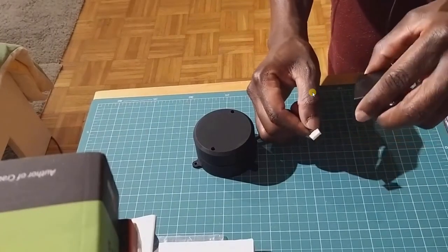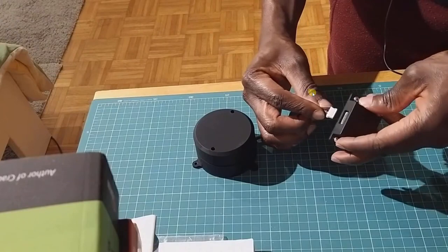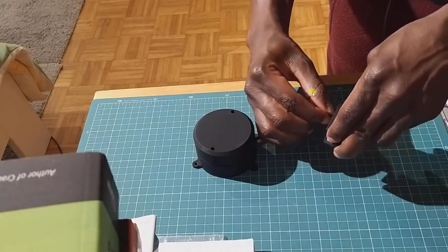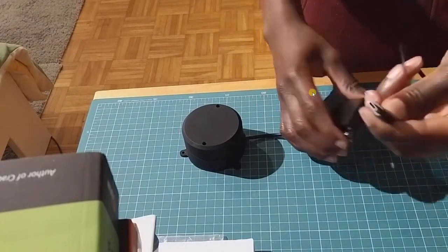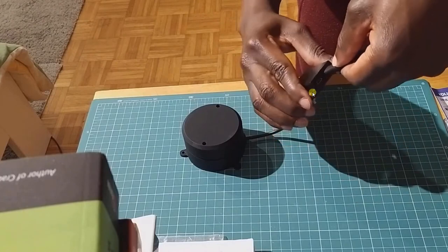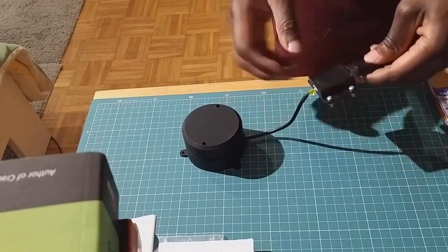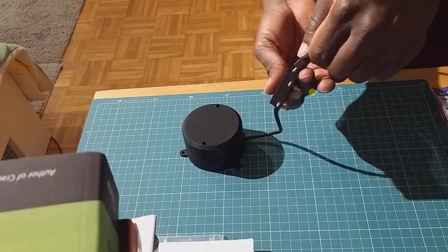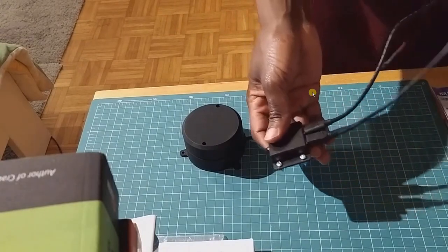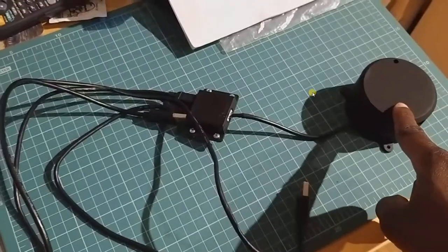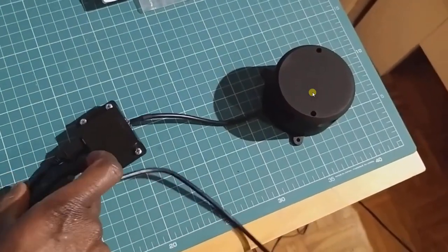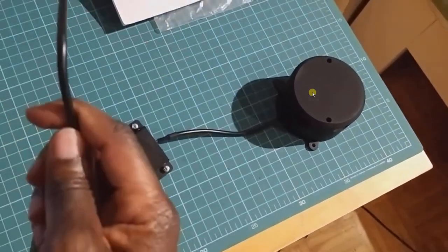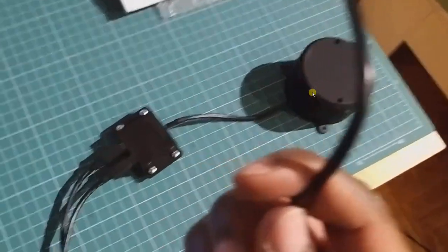There is no need to be very careful as I am doing right now, because it's self-evident which direction it goes. So just plug it in and connect the data on the USB-C. And then connect the power on the micro USB. So LiDAR to the USB hub or USB splitter, and then from the USB splitter, you have one that goes to your computer through the USB-C. This is for the data.